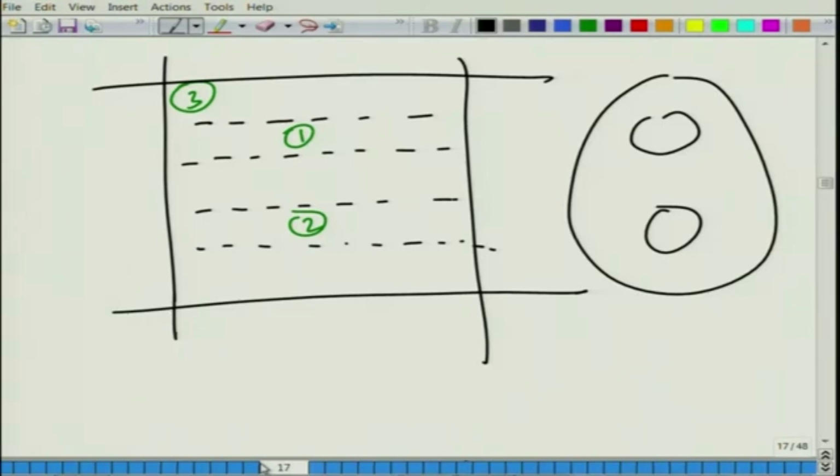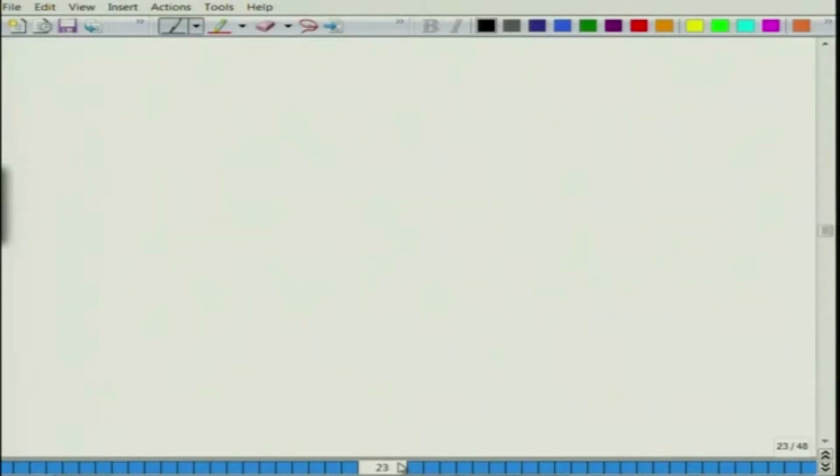So, basically let me write down the equations for this duct with the understanding that we still use a control volume approach. We have to take a control volume here, find out the fluxes that enter inside, go outside, and then the ones that go here, and equate them to the temporal rate of change. So, then you have the momentum equation here, continuity here, momentum here, continuity here, by using a control volume approach. This is going to be a little bit algebraically tedious, but hopefully when we do a systematic job we can overcome all the challenges associated with it. So, let me write down, that was slide number 17. I will go to slide number 23 and start writing down the equations for the different ducts.